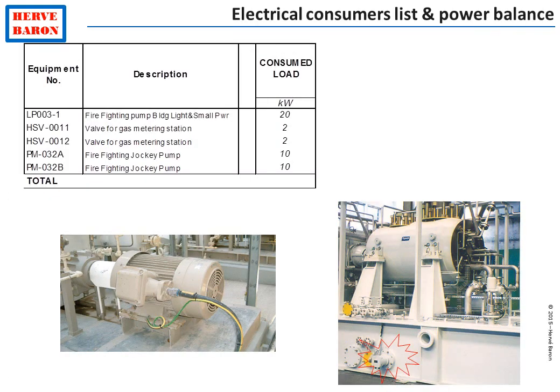The starting point of the electrical engineer is to draw the electrical consumers list. It consists of making an exhaustive inventory of all plant electric power consumers. These include obvious process consumers such as pumps, as well as some hidden consumers such as this lube oil heater inside a compressor package.